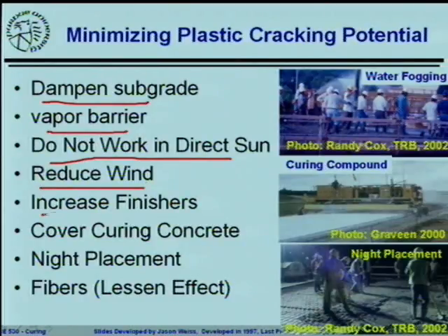Increase the number of finishers. This is essentially the same as asking your finishers to finish faster. Get it finished, get your curing compounds on, get your water on top, go as quickly as you can. Cover curing the concrete. Obviously, that's as easy as it sounds, placing something over it. You cut down on the evaporation rate. Night placement, you tend to have a lot less wind.